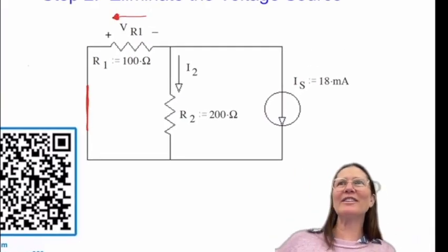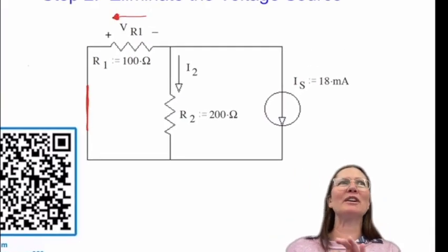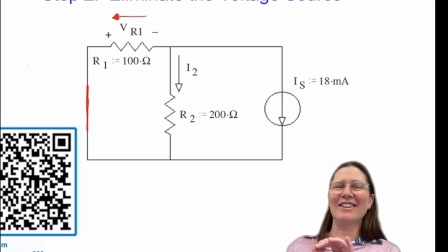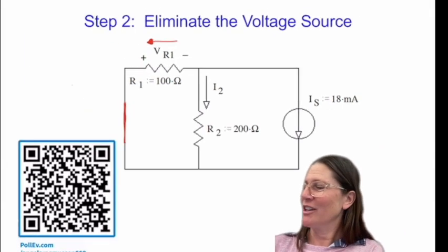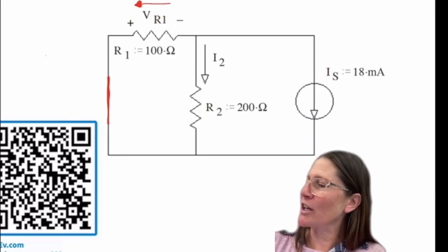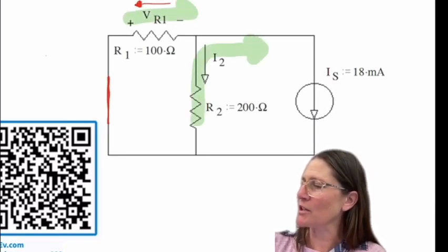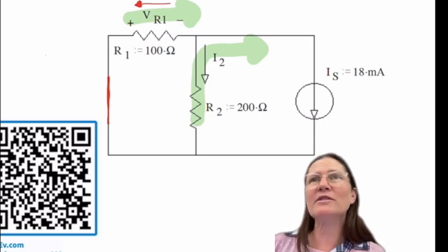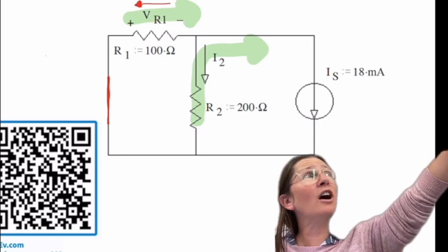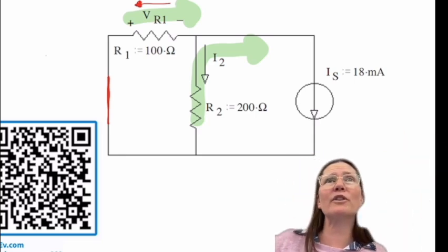So it looked like a consensus on the value, but the polarity was not in the right polarity. So if your current matched the flow here, it would actually be going into this node to match the polarity going in there. But because the wire is drawn opposite that, it's going to be a negative of the current divider.